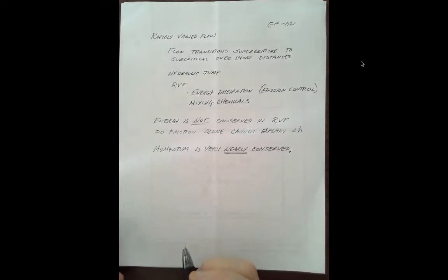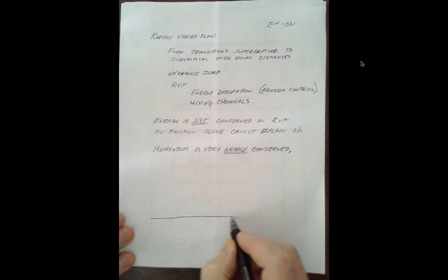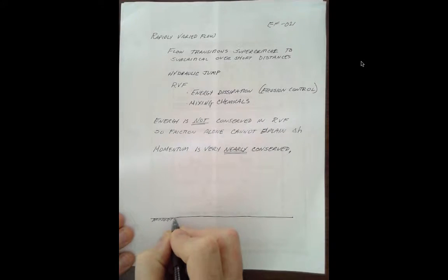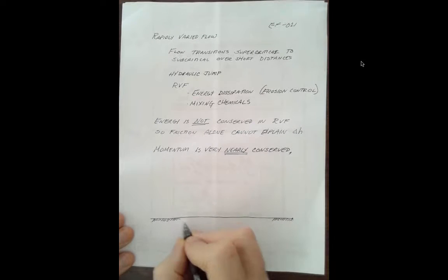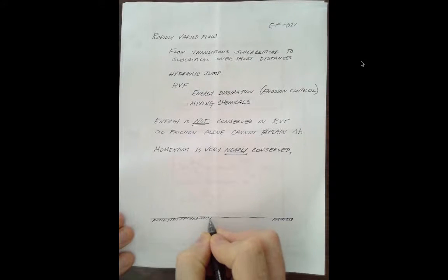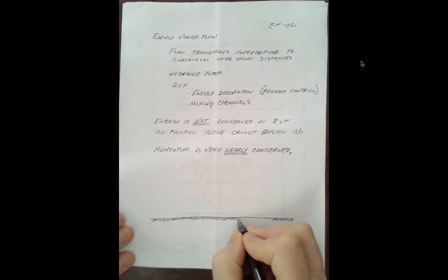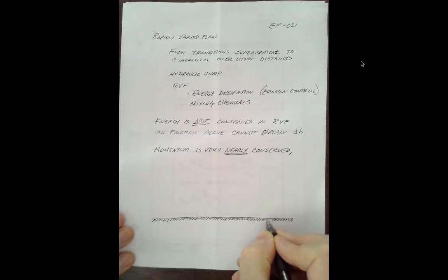Okay, so let's consider just first a definitional sketch of a hydraulic jump. Let us assume that we have open channel flow occurring on a channel. In this case, it's drawn essentially flat, although the flatness is not a prerequisite for a hydraulic jump. In your laboratory class, when you take it, we'll use flat or pretty shallow slopes to generate the hydraulic jump, simply because it's easier to produce the phenomenon in such a situation.